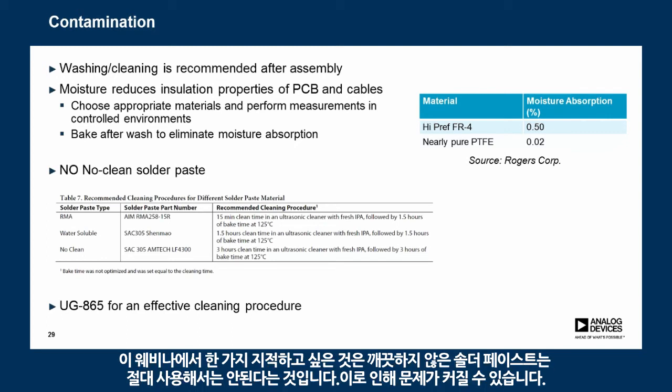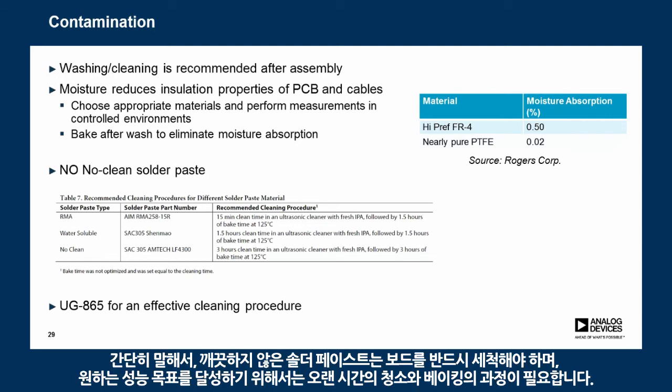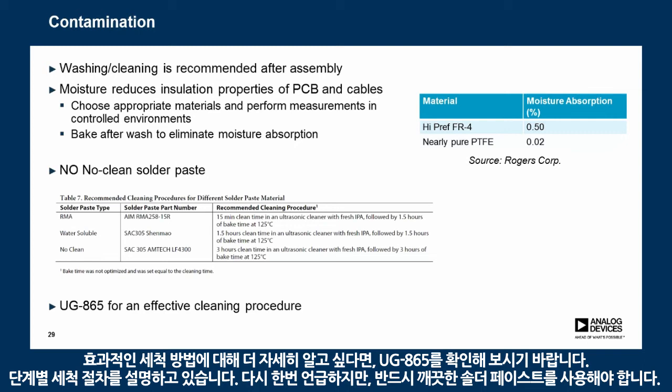And one thing I really want to point out in this webcast is to never ever use no clean solder paste. We have been bitten by that, and I actually did an experiment in lab where I found out the different cleaning procedures for different solder paste materials. So long story short, with no clean solder paste, you actually still have to clean the board, and it takes a very long time to clean it and to bake it for us to reach our performance target. If you want to find out more about an effective cleaning procedure, check out UG 865. It illustrates a step-by-step cleaning procedure. And again, I can't stress enough, do not use no clean solder paste.